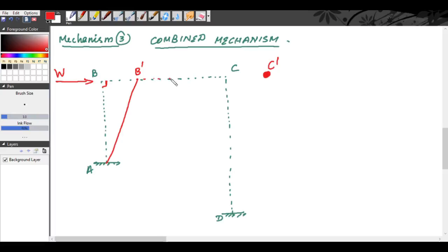So this is your beam now. For this beam, there will be a concentrated load of W0 at the mid. The distance is 2 meter, and here the distance is 2 meter. Now the next hinge formation will be at this point. This is E, right? So at E dash, you will have a hinge formation.